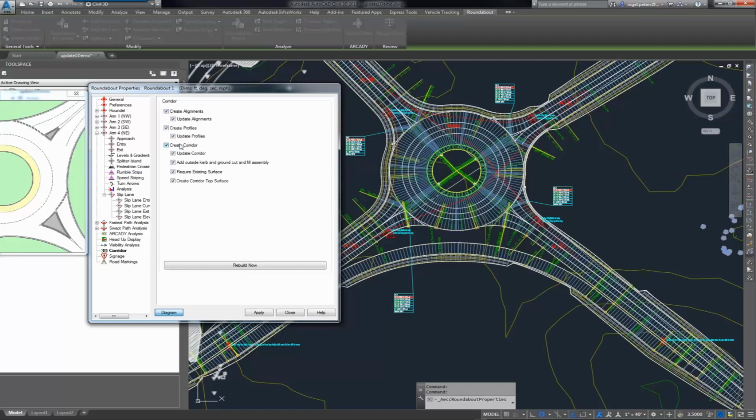You can use this to create a roundabout in 10 clicks. You can have a roundabout that conforms to the standard, and then you can just delete the vehicle tracking roundabout if you want, and you've got your roundabout corridor and maintain it all yourself. Or you can keep the vehicle tracking roundabout, edit it, maintain it, and allow it to update. There are multiple workflows for this. So even if you're just doing a simple cul-de-sac and you don't necessarily want vehicle tracking roundabout in there, you can create yourself a dead-end cul-de-sac turning circle for a corridor in, again, about 5 clicks.